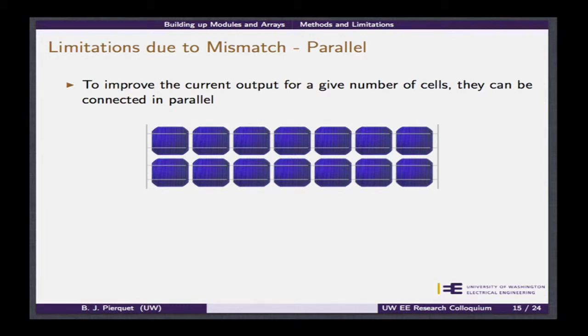That 0.1 volts is essentially going to mean that you want to try and equalize the voltage across here. And so you're ultimately going to be pushing current back into the other one. And so if that's a large enough disparity, you'll ultimately be able to push current back through the whole entire stack. And certainly that's a bad idea.